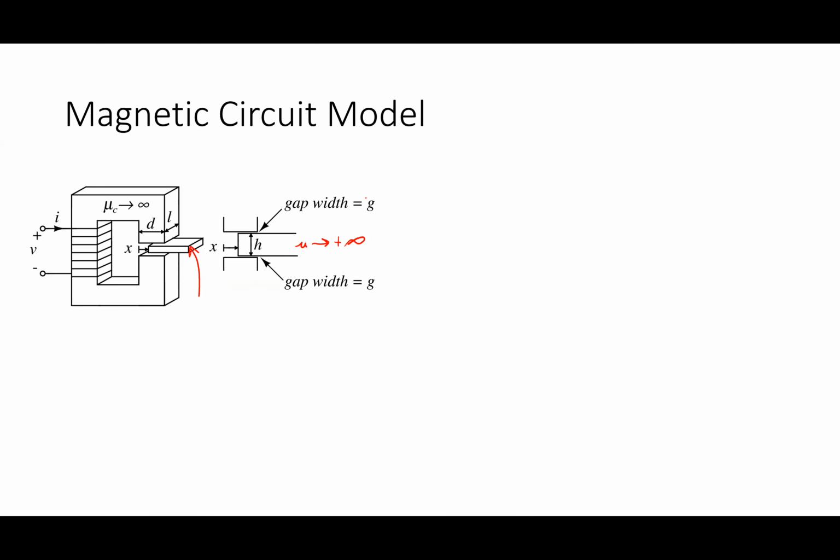All right, so help me out. Help me draw the magnetic circuit model for this thing. Where do I start? My MMF source, which will be N times I. Now, which way does the flux go in this thing? Clockwise. My thumb goes in the direction of the current, my fingers curl around, and it's going to go clockwise. At least one part of one question on the exam is going to be: tell me the direction of the flux. So just be prepared for that. This guy's going to go up, and it goes here and around, always in a circle.